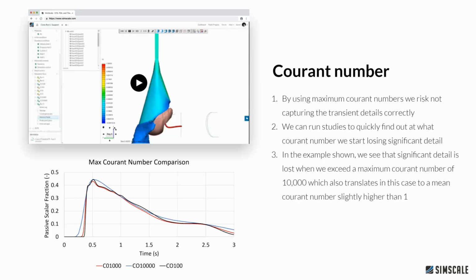So what you can see is the blue line, which is the highest Courant number, that's at 10,000, generally speaking has a similar trend to the other two. However, what you can see is we've started to lose detail. So it starts increasing early. You don't get those little humps at around 0.5 seconds. And generally speaking, it doesn't follow the red and the black line.